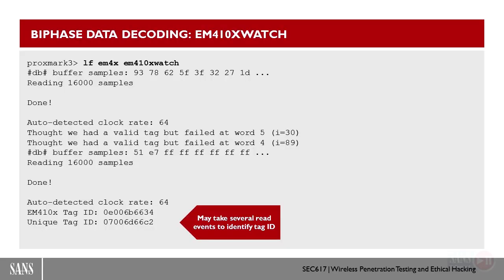Let's go now do some of that analysis. We know it's a 4102 series card, so let's evaluate the card as a 4102 series card with the Proxmark. Low frequency EM4X series, and we're going to watch for EM410X series cards with EM410X watch.